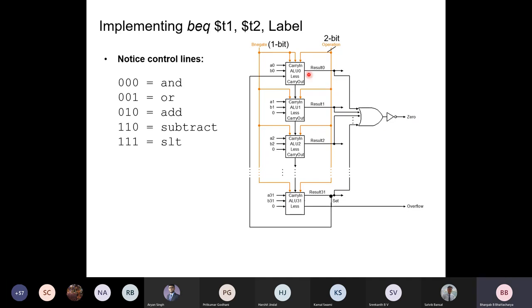And so therefore, this simple ALU can perform addition up to 32-bit operands, subtraction, then logical AND, logical OR, SLT, and branch EQ. We have a small ALU that can perform these basic sets of instructions. The output 0 becomes 1 when the branch is taken, because all the bits will be 0.